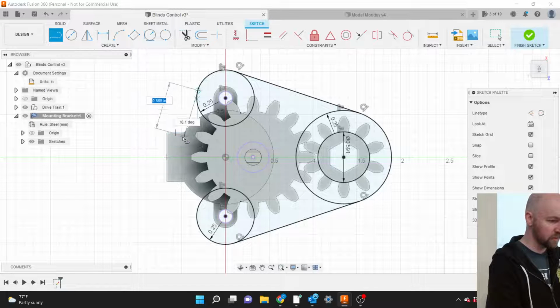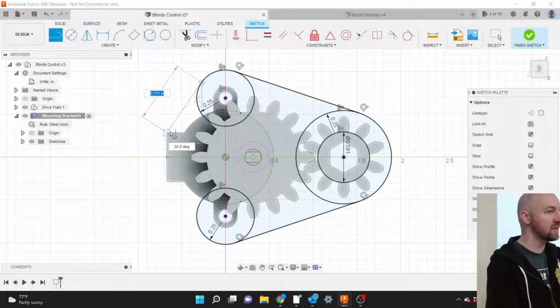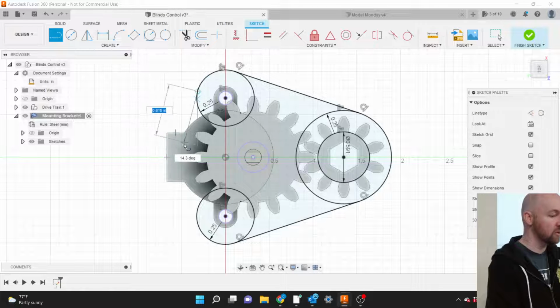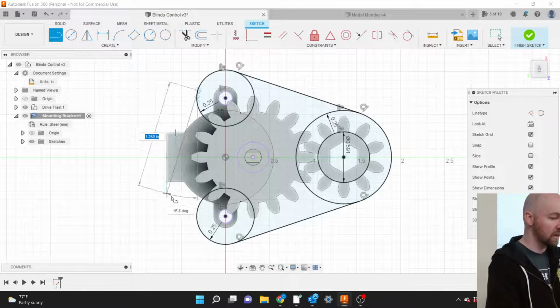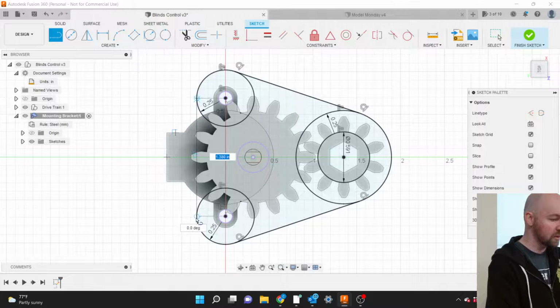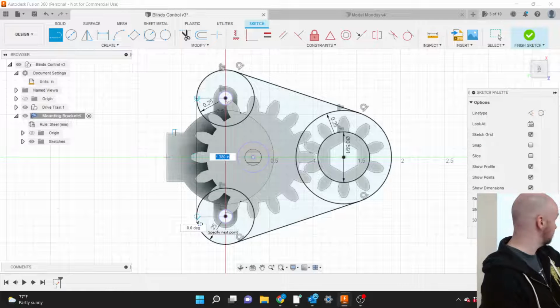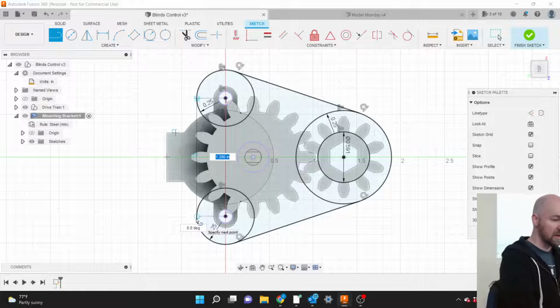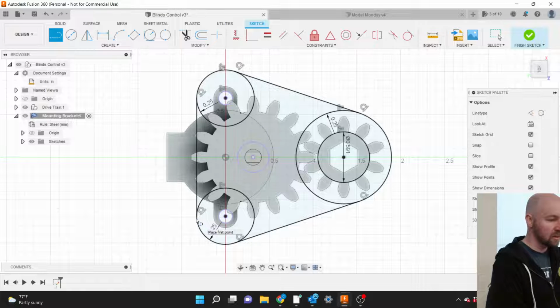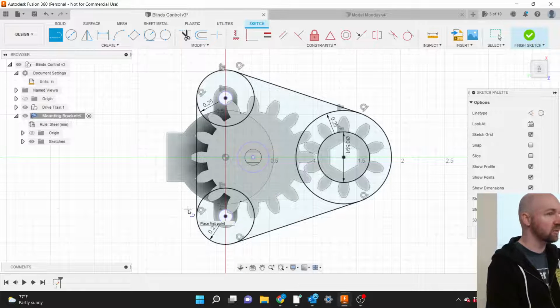Oh, there we go. So here, if I'm holding down the shift key, now you can see that it is forcing that tangency to the first circle while I continue to hold down the shift key. And I can move it over and hover over where about tangent looks. And then I get those two tangents. Again, just holding down the shift key the whole time I was clicking there.